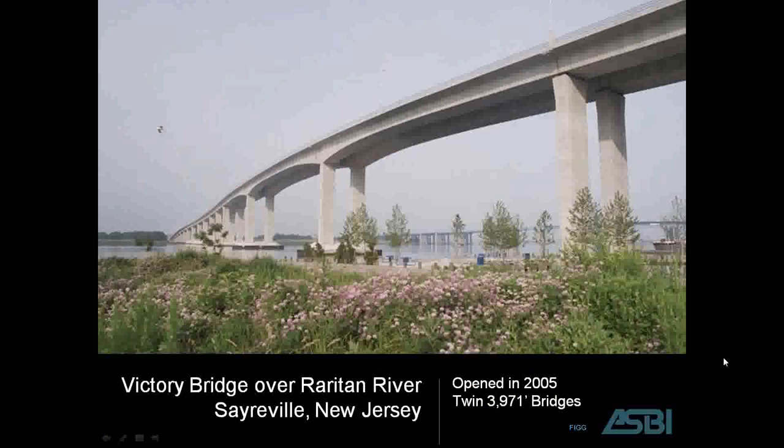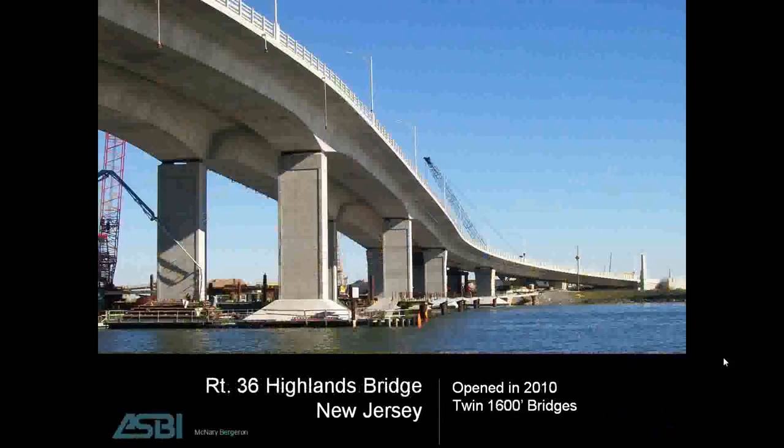Here we see the Victory Bridge over the Raritan River in New Jersey. And here are the spans. The approach spans are 150 feet, and the main navigation span is a 440-foot precast span. That is a record in North America. This bridge has an integral wearing surface that I discussed earlier. The first of the twin bridges opened 15 months after award of the project, and the second was opened 9 months later. So precasting expedited the project. This also utilizes a precast substructure, which I'll talk about in the future here.